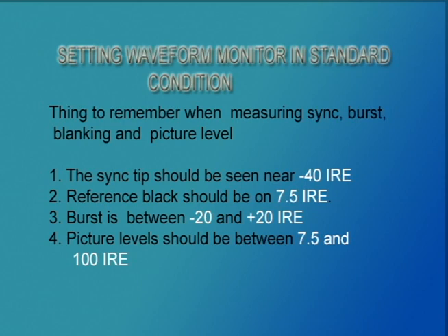Before you can measure the sync, burst, blanking, and picture level components of the NTSC signal, you must calibrate the waveform monitor into a standard condition. Let's assume that you have already connected all the cables.